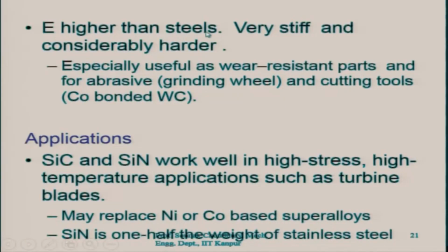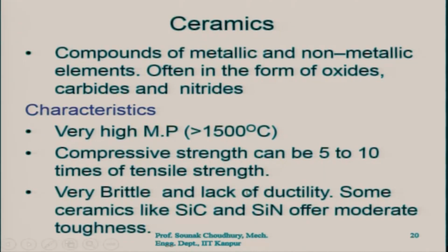Young's modulus is higher than steel; they are very stiff and considerably harder. Especially useful as wear resistant parts and for abrasives, like very often ceramic particles are used in terms of silicon carbide, for example. We said that silicon carbide and silicon nitride have moderate toughness.